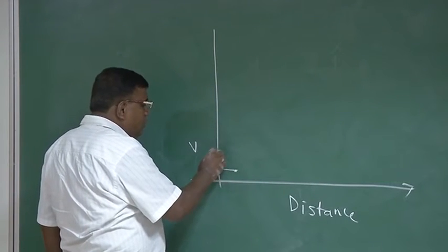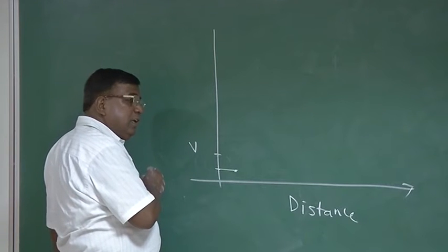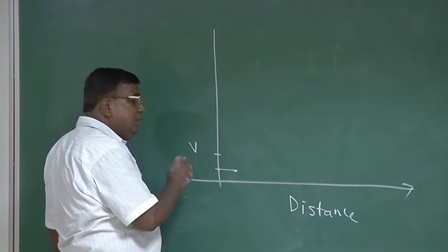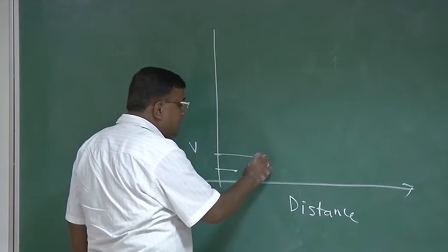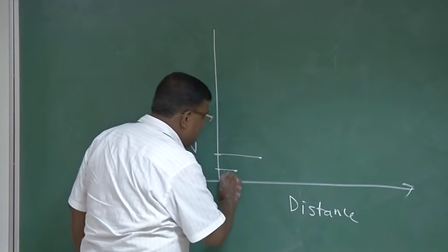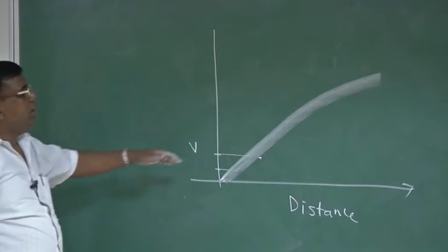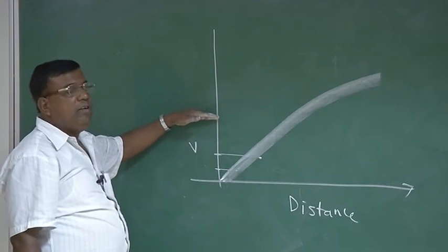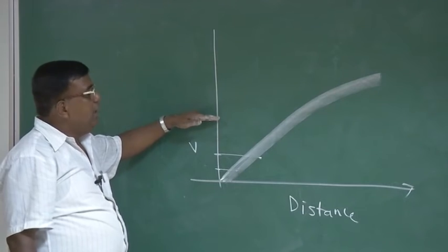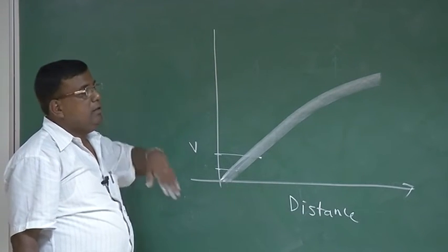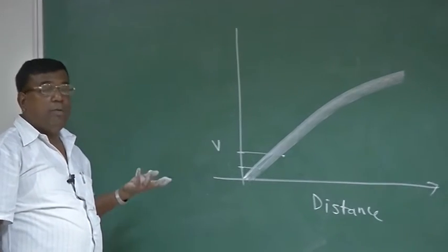As the speed at which the airplane engine has failed increases, the braking distance will go on increasing. So let us say that variation is something like this. I can calculate, assuming different speeds at which the engine has failed, the braking distance by using our formula SB.